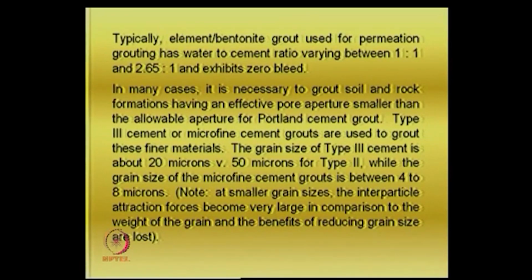So, you have to balance the gravity and the interparticle forces, so that the grout is able to go to the required destination. The weight is required to some extent, but at the same time if it just starts getting suspended in the form of a few particles in the grout, then the purpose is not served. There should be a balance of forces of gravity as well as interparticle forces, and that is where the choice of the grout is made.